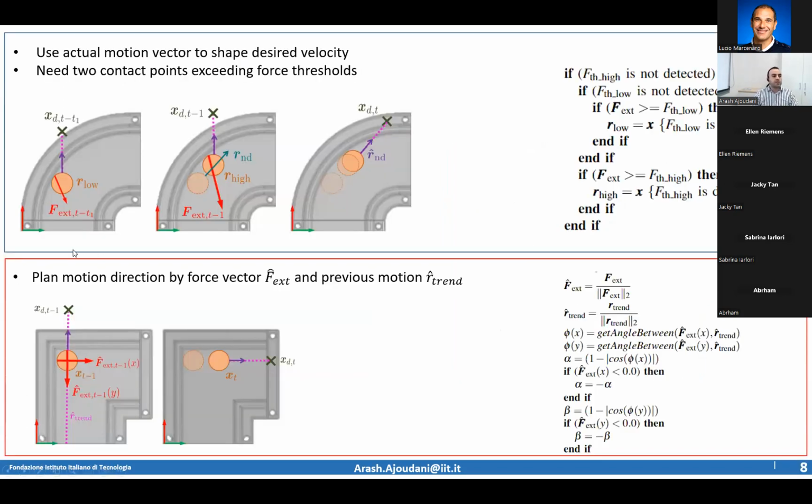Just to give you an example, if you have soft constraints, you can process data, always relying on the force data that you're getting from the interaction with the environment, and you can update your path and your equilibrium pose to always comply with the soft constraints that you have, without even knowing what the surface looks like. It's like opening a door, right? You have a physical constraint from the environment, but you use those constraints to be able to slide on this surface.